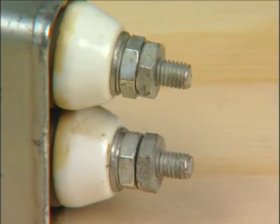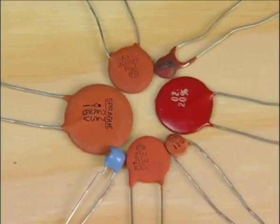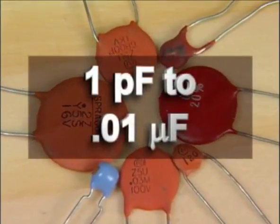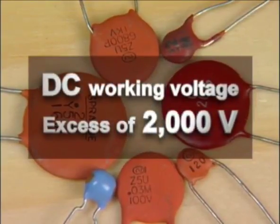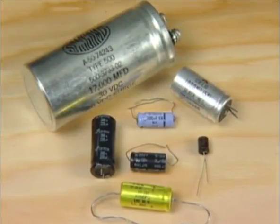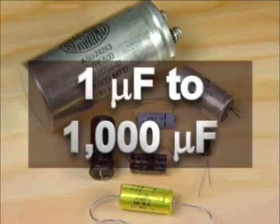Other types are also used. Ceramic capacitors use ceramic as the dielectric and a film of silver for the plates. They range in value from 1 picofarad to 0.01 microfarad and have a DC working voltage in excess of 2000 volts.